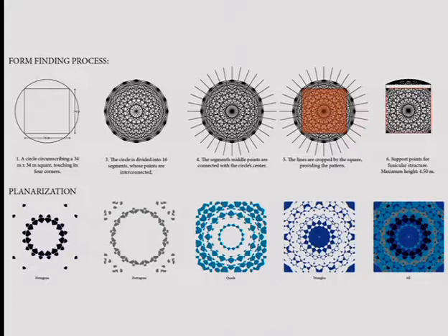Well, so far, we're not talking about planarization, but the shapes we get out of it is that, we've got a few triangles, the blue one. The cyan ones are quads, so they need to be optimized. These ones are pentagons, and the ones on the left, they are hexagons. So out of that, I think we have less than 1/5 of the surface which is already working because it's done on triangles. The other ones are shapes, which are completely useless because they're doubly curved in the way they are.